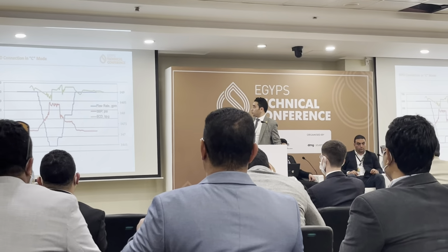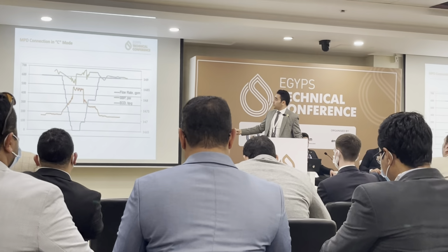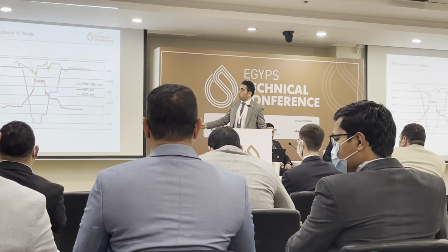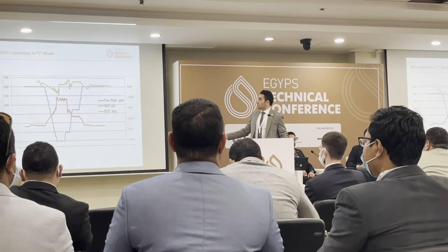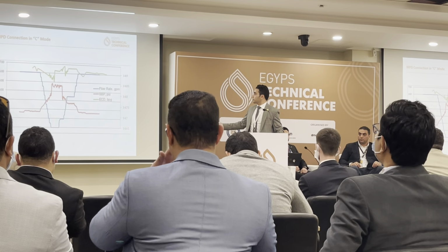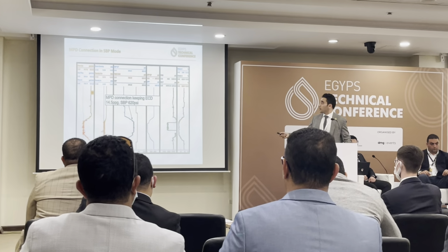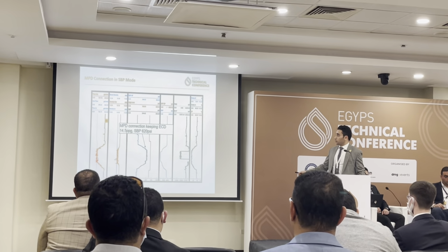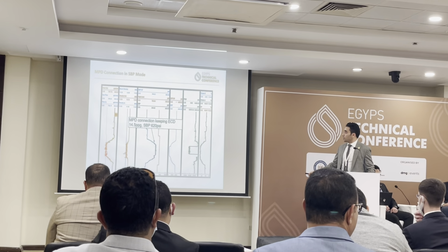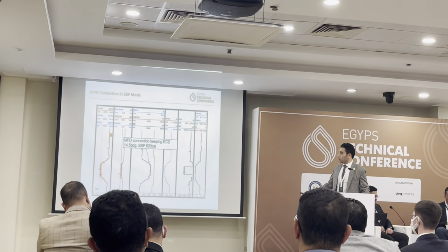And as we see, we were starting at 14.93, and as represented by the green lines, the difference between the highest and lowest ECD imposed on the formation during the connection is 0.09 ppg, which is 70 psi. And here's the MPD connection in surface choke pressure mode. We kept during the connection 14.5 ppg with surface choke pressure of 620 psi the whole connection time.